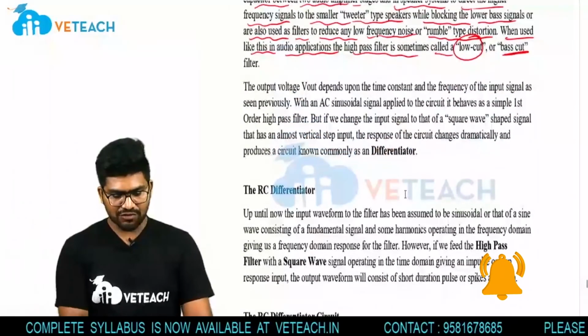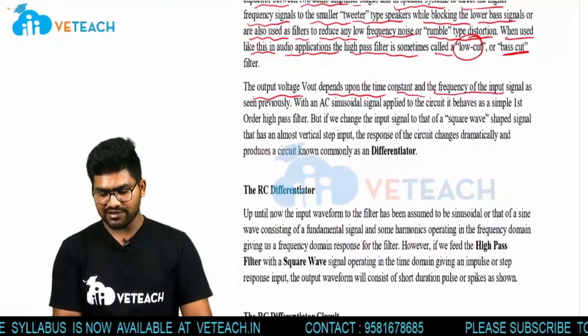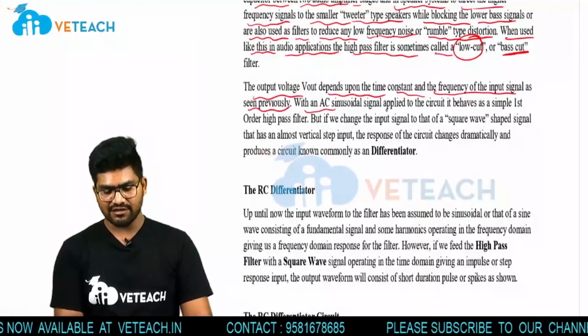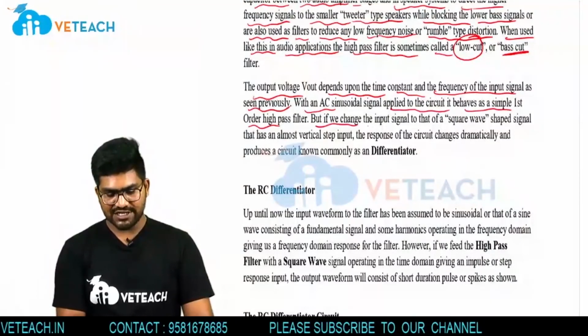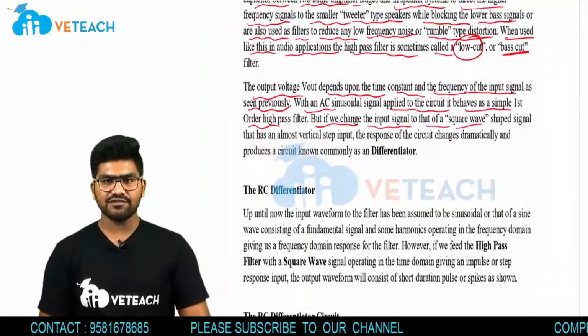Now the output voltage Vout depends upon the time constant and the frequency of the input signal, as seen previously. With an AC sinusoidal signal applied to the circuit, it behaves as a simple first order high pass filter circuit. But earlier we have given a sine wave or a DC wave as input.